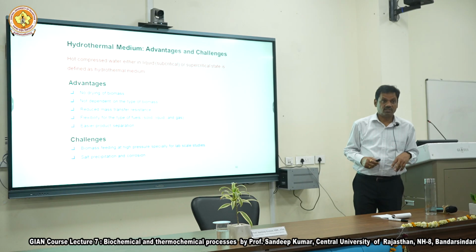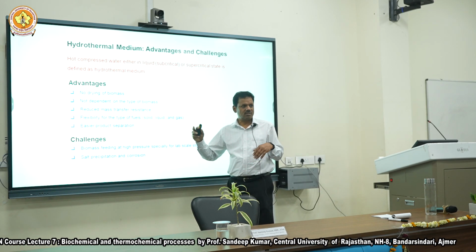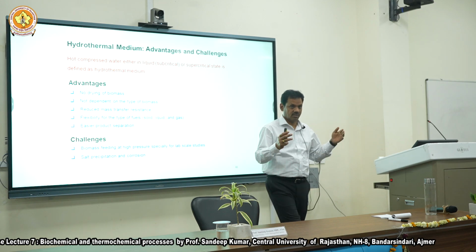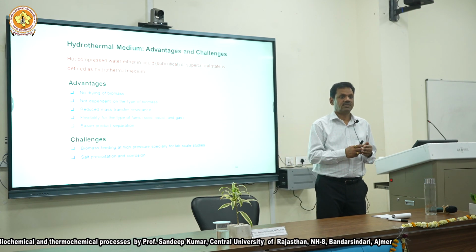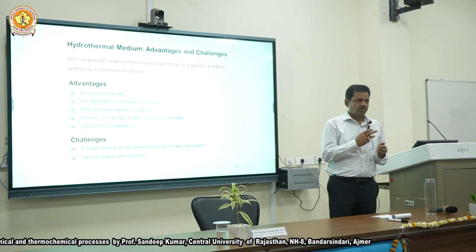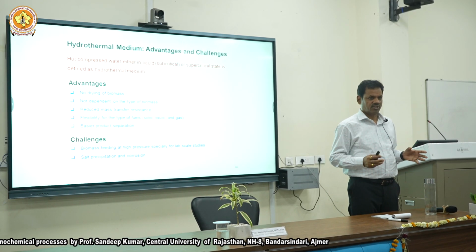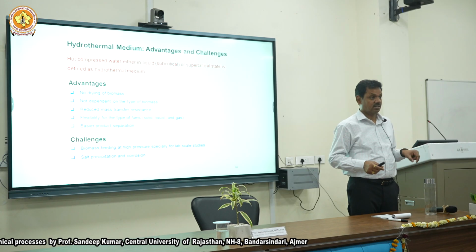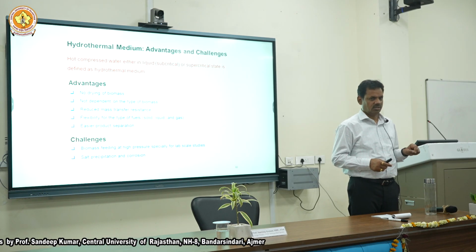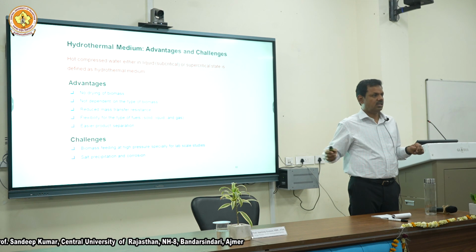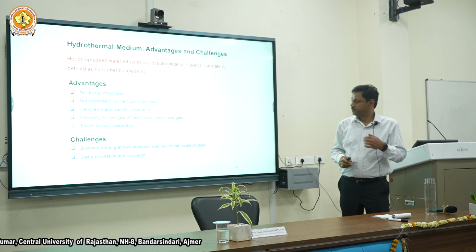The only thing is you have to change the reactor, and the reactor now becomes high pressure, because you have to pressurize it. That's the challenge. If you have a pressurized reactor, that means you are putting in a lot of metal, a thick, big reactor, so that's the initial capital cost. But we are not dealing with corrosive chemicals, so it's a trade-off.